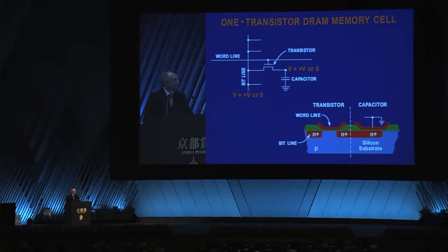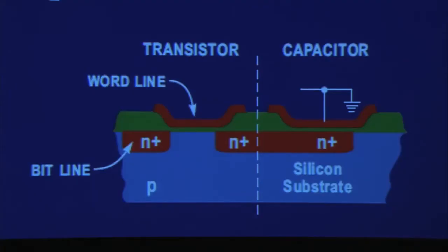The drawing below shows a cross-section of a field effect transistor and a capacitor forming a 1-transistor memory cell. I won't attempt to describe this in detail. A beauty of the integrated circuit is that the conducting layer forming the gate of the transistor is common to all the gates, so that it also serves as a wire selecting a particular row of cells.